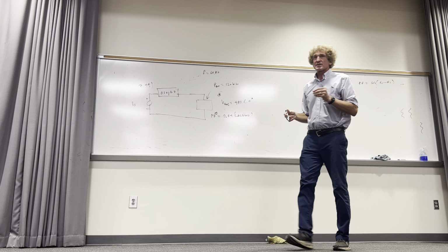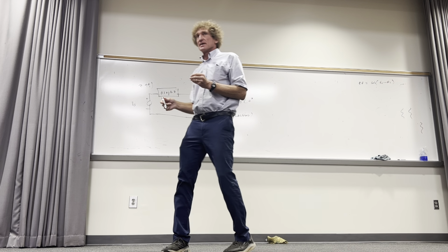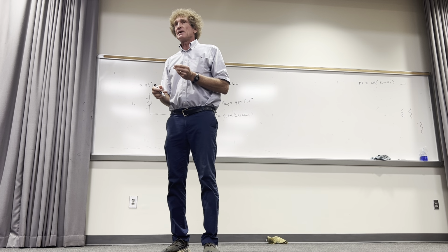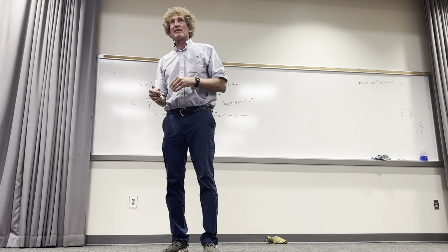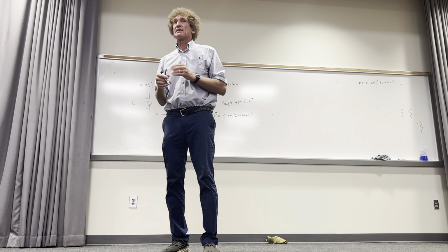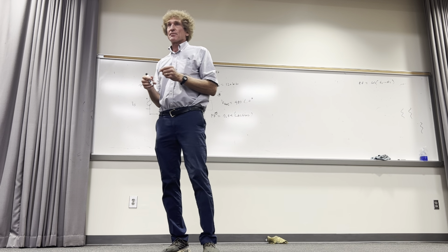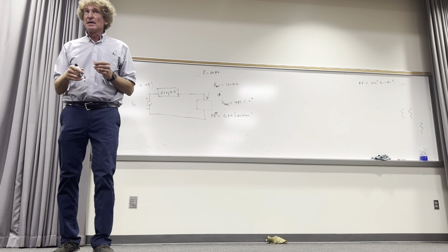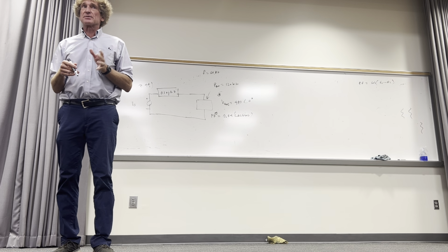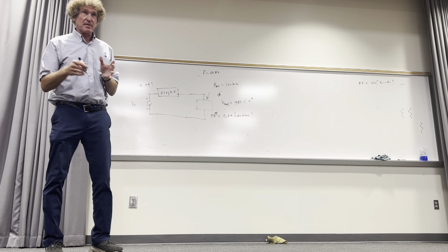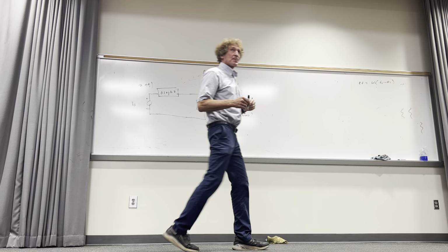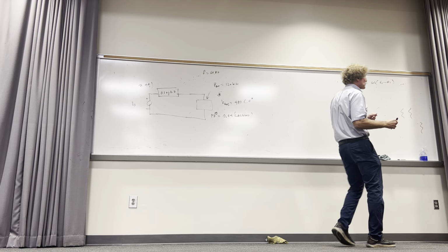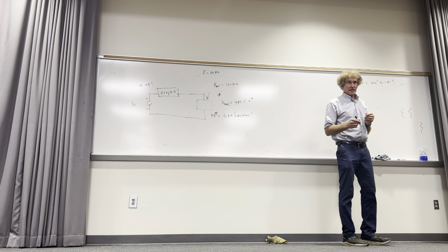The problem with just stating the power factor by itself is cosine is an even function, so cosine of x is the same thing as cosine of minus x. Said a different way, the cosine of 30 degrees is the same thing as the cosine of minus 30 degrees. I hope I made that clear to everybody. So they have to do one more thing. They use the term lag or lead.